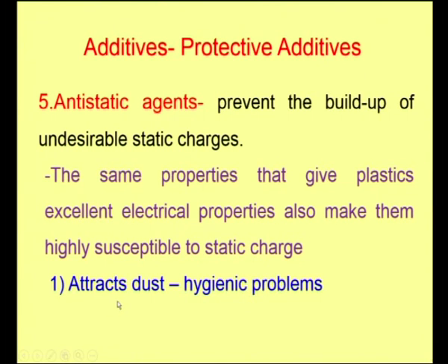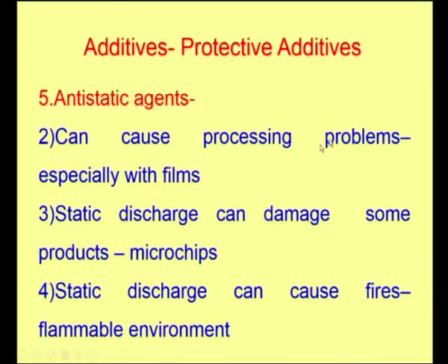Hence, this will attract dust. When you have static charges on the surface of a product, because of the electrostatic attraction between the dust particles and the static charge on the surface, dust is more frequently collected on the surface of the product. This may result in hygienic problems when it is used in hygienic applications like in hospitals. And then it can also cause processing problems, especially with films.